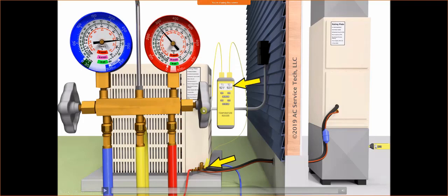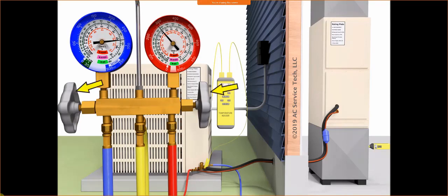All right, our gauges, everything is outside there. It's usually pretty close to where we need it to be from a ballpark standpoint. Maybe talking about a couple of degrees with the insulated line, but you're going to be more accurate measuring here. Okay. So once again, that needs to be within 3 inches of that surface port in order to compare your pressure and also your temperature at that location. One more thing that you want to make sure of is that the gauge set handles are shut. So before you even turn that system on, you want to have that manifold gauge set connected, your handle shut, and then you can go ahead and turn the outdoor air conditioning unit on.